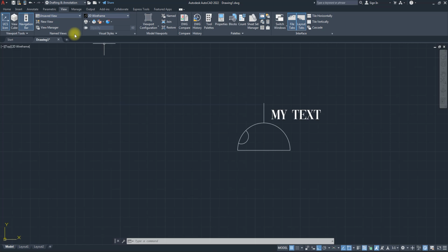Visualize panel was turned off. Remember, I talked about workspace. For a workspace, things that are not necessary for a particular workspace will be hidden. So that's what is happening. That doesn't mean these are all the panels you have. It's just for the particular purpose. Visualize was turned off because there's nothing you really want to visualize in 2D lines. If it was 3D shapes, you can now start saying you want to visualize how it's going to look in different visual styles. Do you understand?